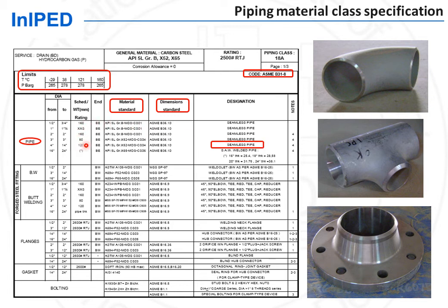The wall thickness is calculated applying the formula of the applied piping design code, usually ASME B31.3. The formula is applied for the pressure and temperature limits of the piping class and for the selected grade of steel.